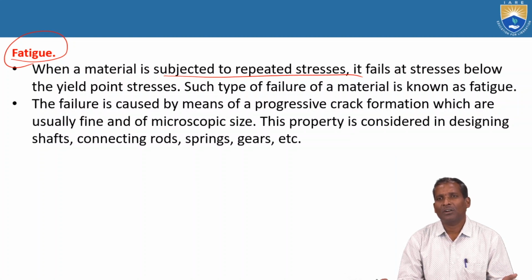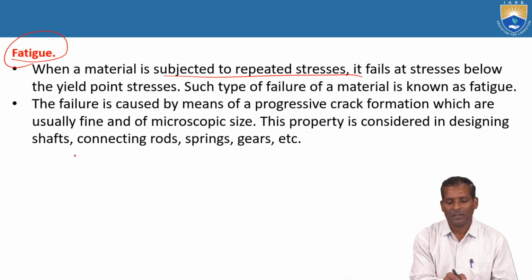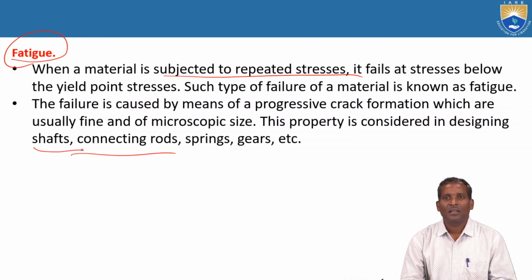All mechanical components are subjected to this fatigue phenomenon. Why? Because these mechanical components are always subjected to repeated stresses. Take for example a connecting rod, shaft, springs, and gears also.